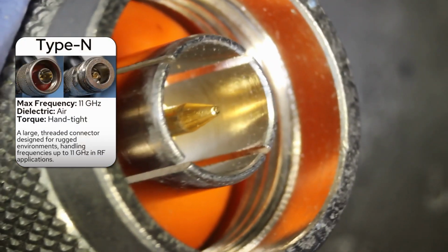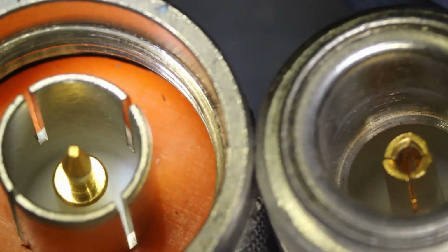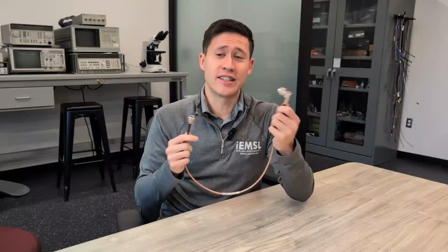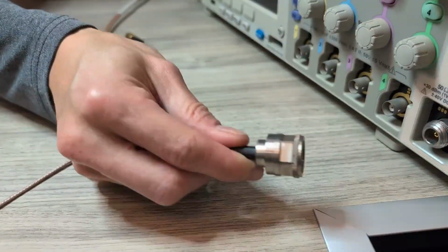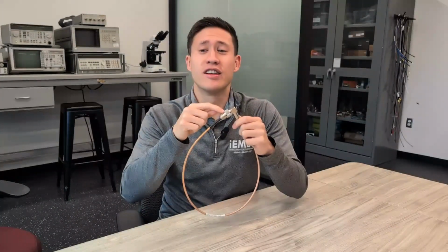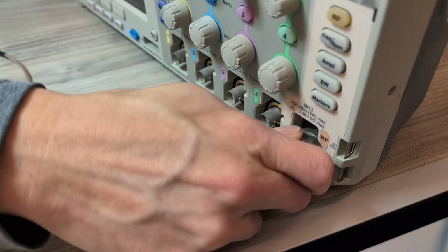Now you'll notice that the type N connector is a lot larger than the BNC connector. Originally developed for use in the military, this large and heavy-duty connector is still widely used today for RF applications up to 11 gigahertz. As before, the type N connector has an outside part that spins freely, while the female connector does not. When connecting 2 type N connectors, spin the outside part of the male connector, which brings the 2 connectors together. Now, this outside part is called the coupling nut, and sometimes referred to as the nut or the collar. The connection is made when it's as tight as you can get it by hand.